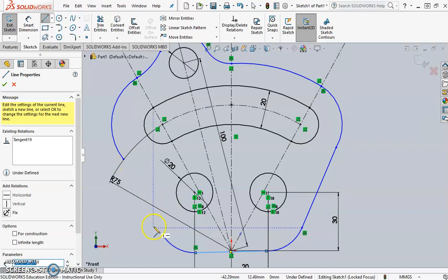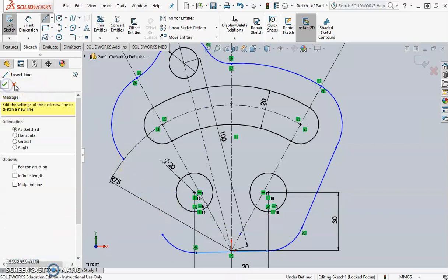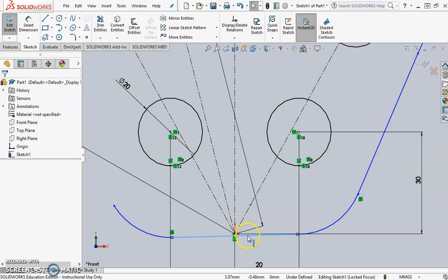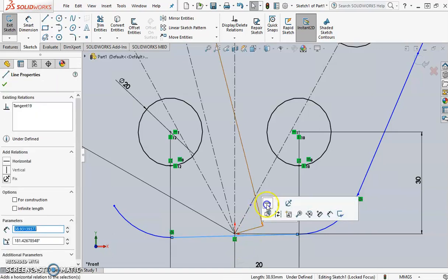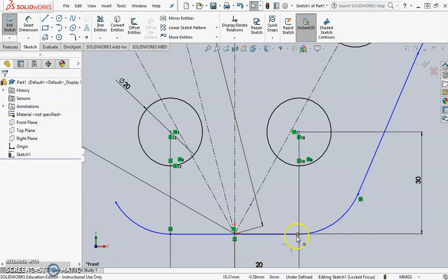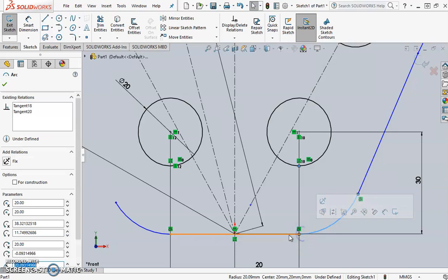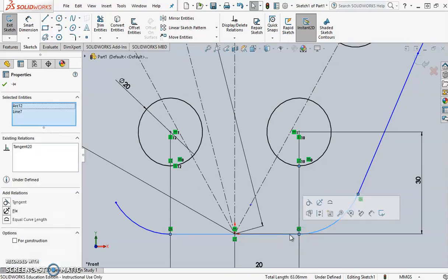So before we put this one in and things go really crazy with all this, let's go back and make all the spots tangent that need to be. So first off, this line that I just drew down here should be horizontal. Okay, this should be tangent. And notice I'm just clicking on the dot. You can, however, select one line, hold shift, and select the other.